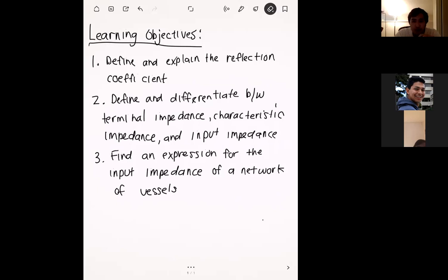Actually, we can use ParaView to test mesh quality. ParaView has a pretty good filter for that. Normally, we use ParaView in this class just to view simulation results, like pressures and velocities, but you can use it to check the quality of your mesh too. I'm sure ANSYS has some features that help you check for mesh quality too.